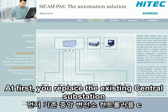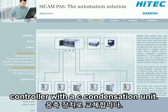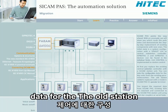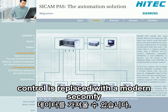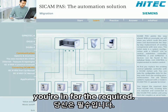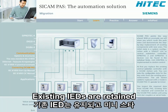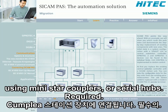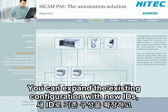At first, you replace the existing central substation controller with a SIEMENS station unit. You can take the configuration data for the bay units from the existing parameterization. The old station control is replaced with a modern SIEMENS PAS-CC operator terminal. You import the required data from SIEMENS PAS. Existing IEDs are retained and connected to the SIEMENS PAS station unit using mini-star couplers or serial hubs. If required, you can expand the existing configuration with new IEDs.